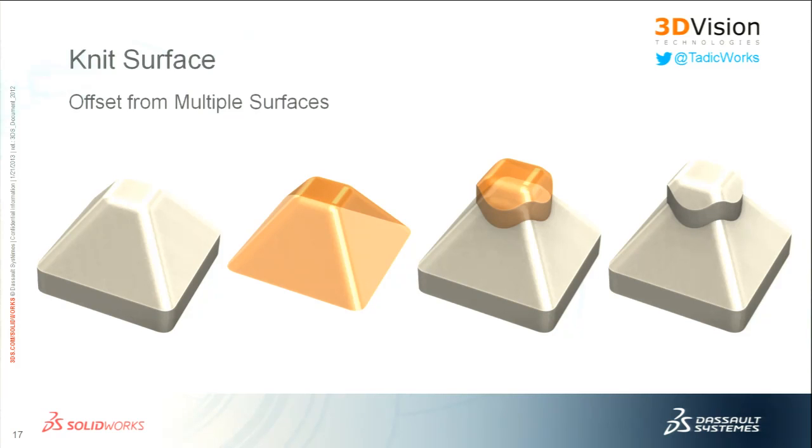Or what I did was scribe the surface, so it just split that into multiple faces. Maybe if I wanted that to be a label, I could then assign a different color to each one of those faces for the letters of my name or something like that. So it gives you three options there. What's that? Oh, absolutely. All these features, just like regular features, are configurable and can be controlled by a design table as well.